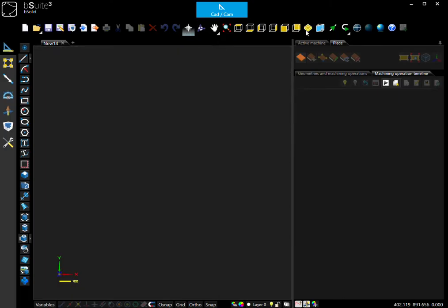You can just hit undo and have another go. Here we've got our icons to enable us to change the view of the window. So we can select orbit, pan, zoom, and flick between the different views as shown in that little wireframe icon there. Top view's great, plan's good, isometric's good, and you can go in and have a look at details on fronts and sides and whatever else. Over here you can change your view to wireframe and change some of the other things that you see on the screen. Finally, the guide, very handy, and also the create article button there for when you're nesting.